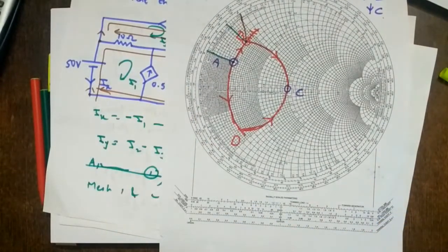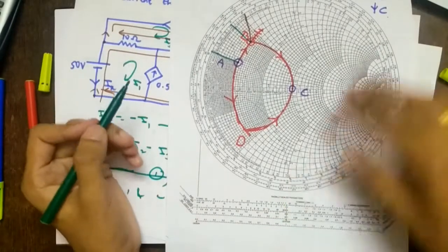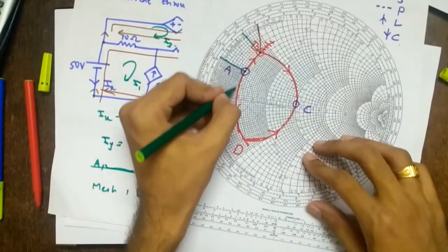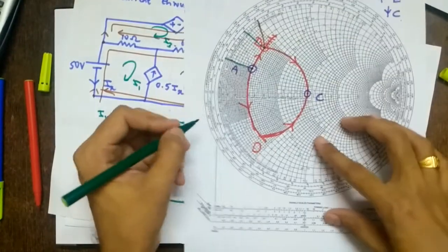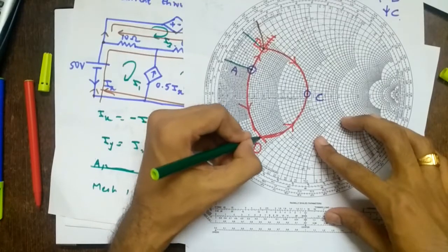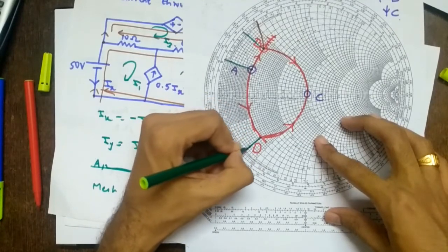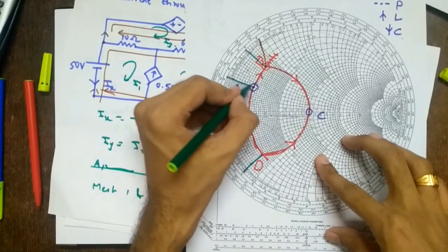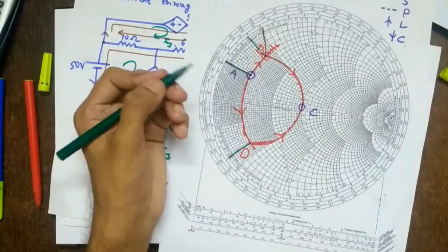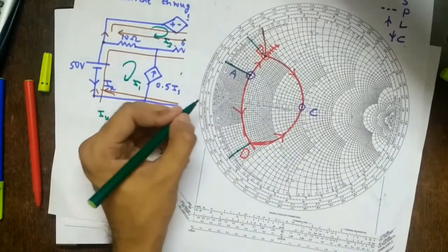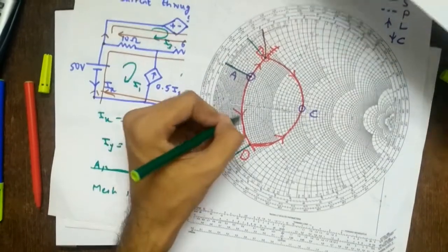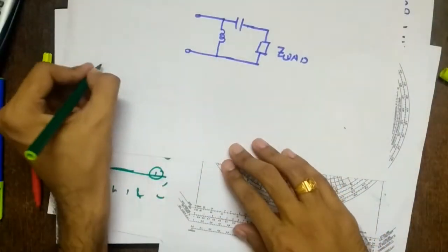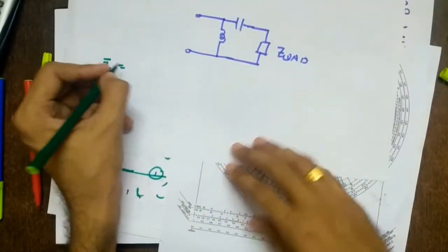The next step is, again, I'll use the green pen to find the reactances. Here we have moved along which circle? Solid, that is the constant resistance circle, so we have to see the solid line. For this point I am coming here, so it is j.4. And this point we already know, for the solid line it was this j.2. But it is destination minus source. And it is a capacitor along the solid line, so ZC bar.